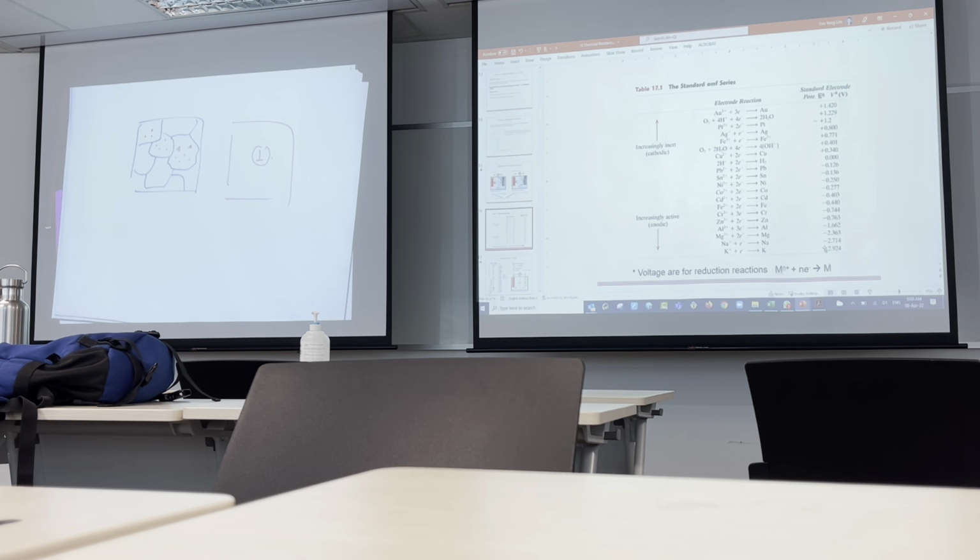Prof, so between coherent and incoherent precipitate, is coherent the more likely one to be attacked in this case? Coherent is less likely, in a sense, because they are all coordinated. Incoherent, there are some bonds that are not connected. Coherent means all the bonds go all the way through. There's no boundary, there are no unsatisfied bonds.